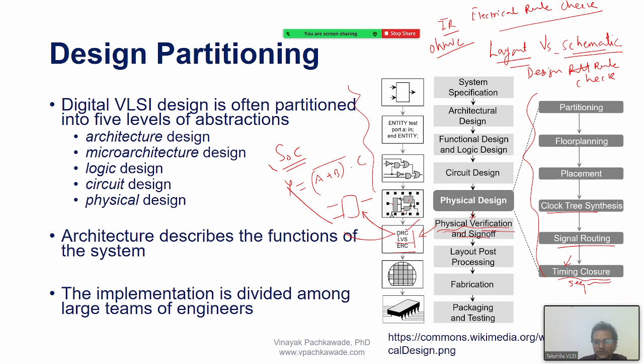Okay, sir. So DRC is design rule check, as I said, and LVS is layout versus schematic. What is your schematic? Like the transistors, whatever, and based on that you have then drawn the layout. So this tool will check. Let's say you have 20 transistors in the schematic and you created a layout, and the layout shows 19 transistors or 21 transistors. By mistake you forgot that.